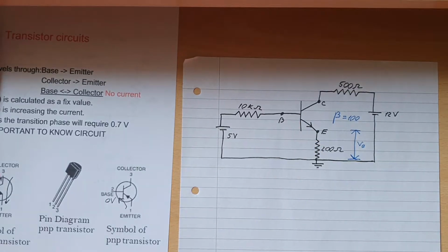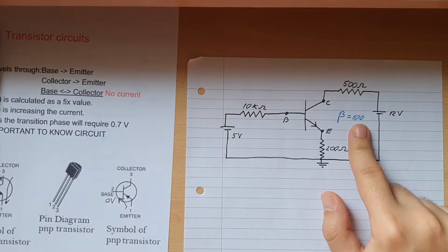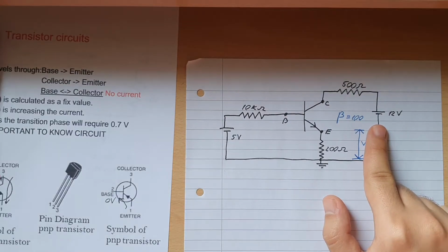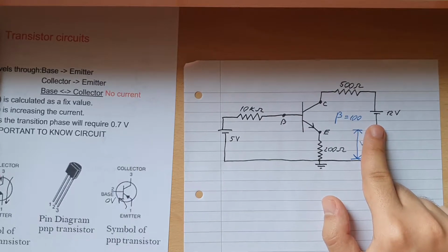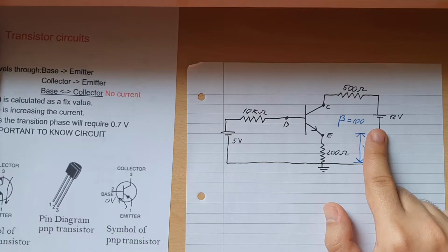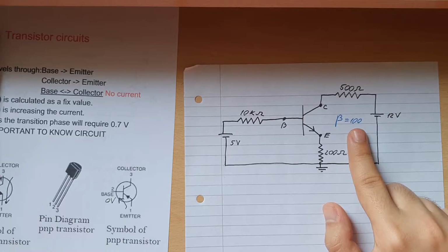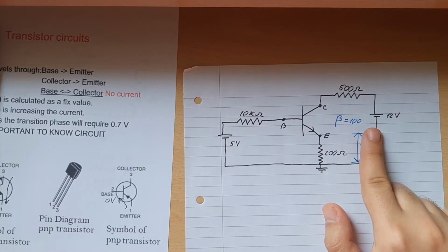This is one of the things that I said I don't really know the answer for, because I was looking at transistors and there are many types of them, and they have different gains. Some of them have range gains, between 100 and 700. Even in books that I read about transistors, they say you can't always trust the reading from the data sheet because they are designed to give you a range. So when you use a transistor, you are not always 100% sure if it's 100 gain or 200 gain or even 300 gain.